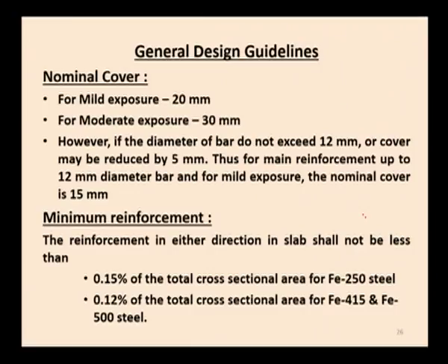In the case of slab, the nominal cover for the mild exposure is 20 mm. For moderate exposure, it may be 30 mm. Normally, as far as our place is concerned, we need to choose these two exposure conditions: one is mild, another one is moderate exposure conditions.